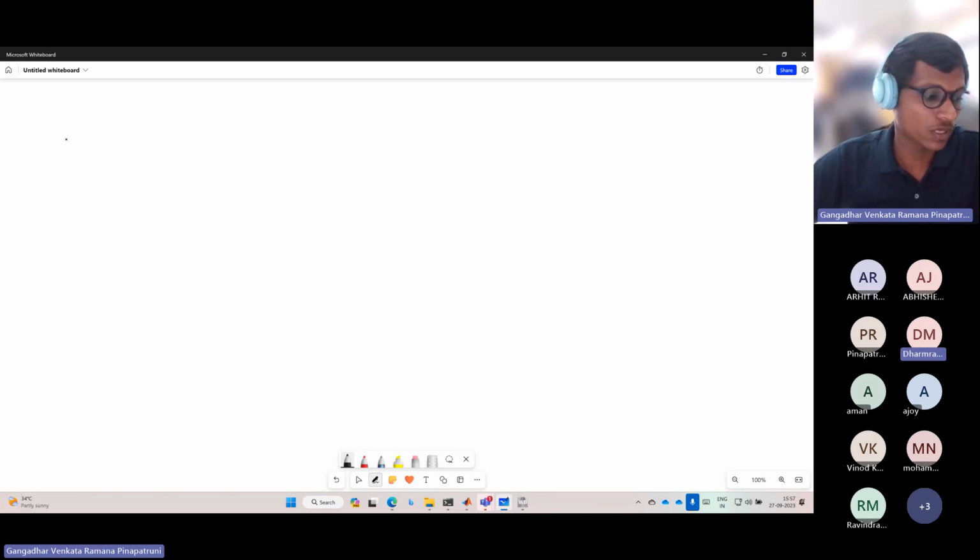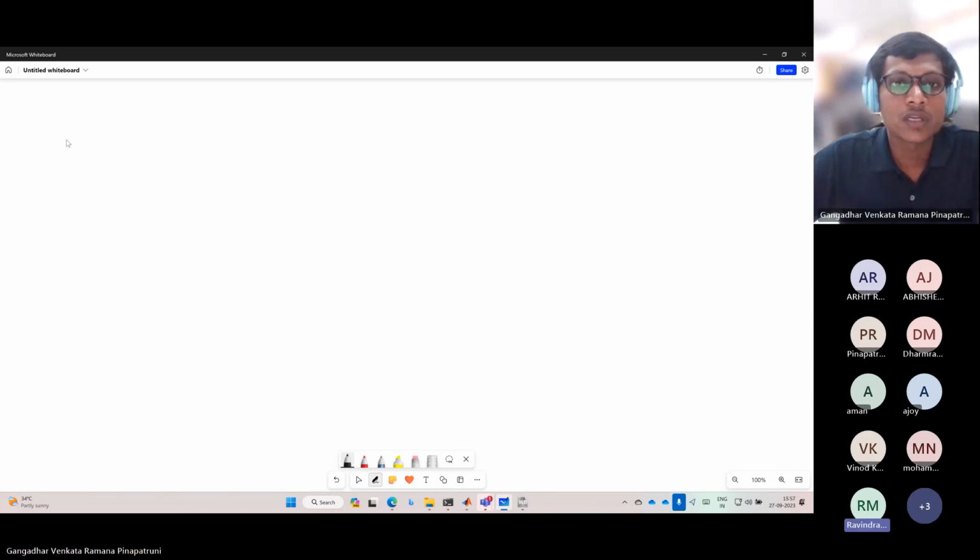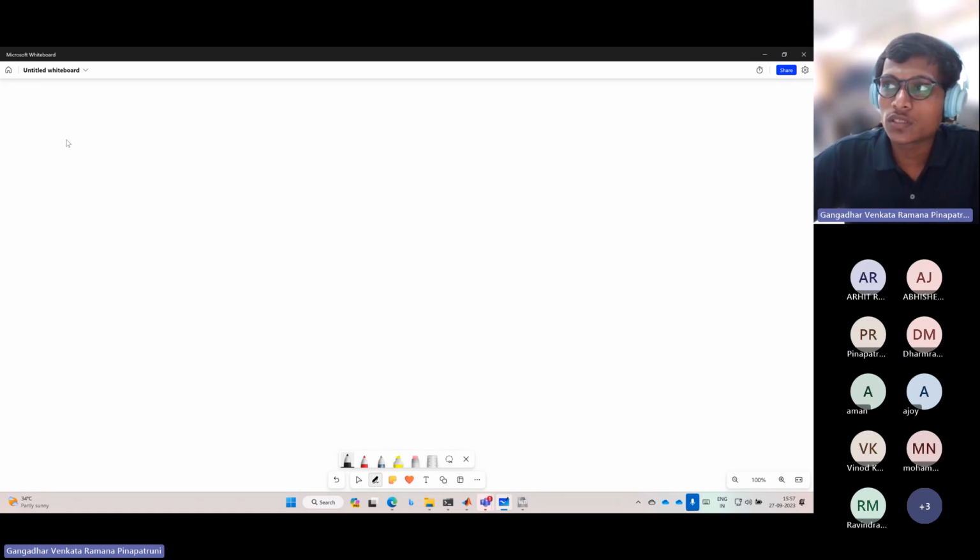Okay, sir, I will help you with that. Vortex flow does not necessarily have to be turbulence. Vortices we can also find in the laminar zone. There we are seeing external flow. Many of us know Reynolds number is quite famous for internal flows, flow through a pipe.